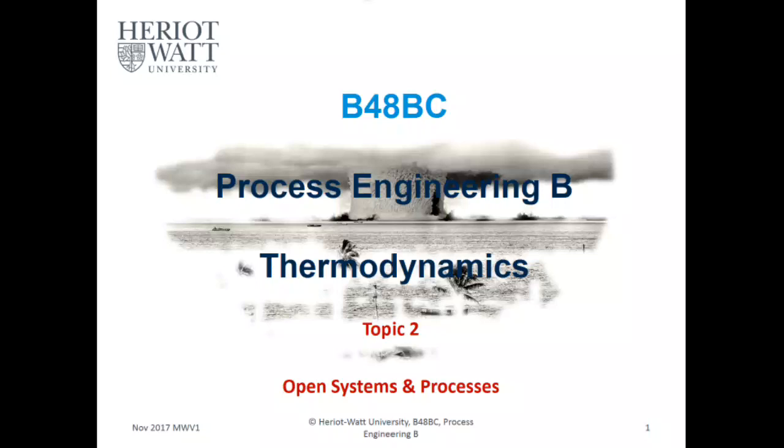And then tomorrow I'll try to finish the open system topic, and then move on to compressor, basically giving you tutorials on compressor design, because the lectures are not that informative on compressor design, but the tutorials are quite good. So we'll work through them. There's ideal gas laws, and there's actually other EOSs like Peng-Robinson and SRK, which you can use in your design if you have a compressor.